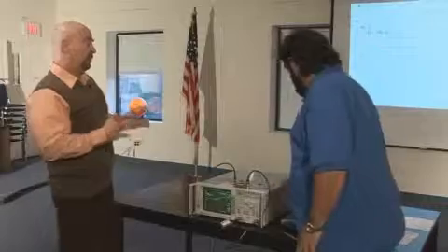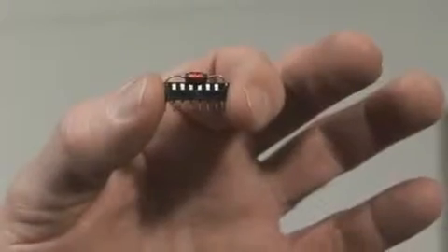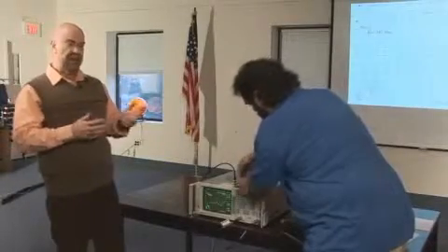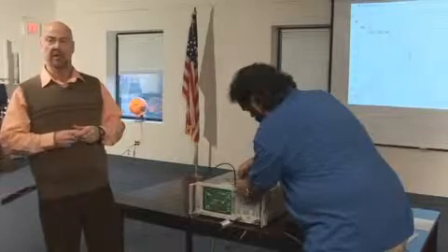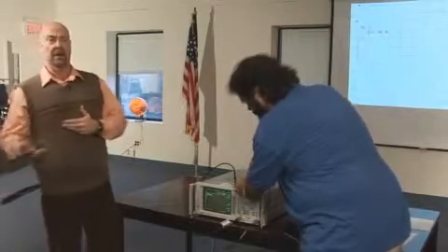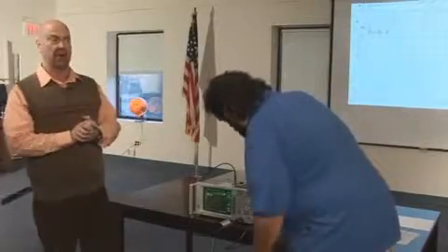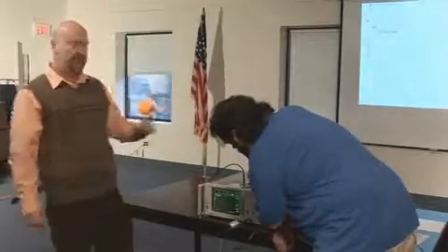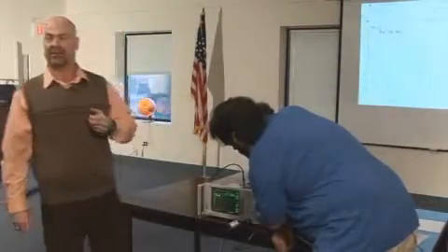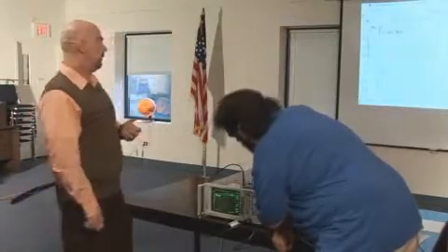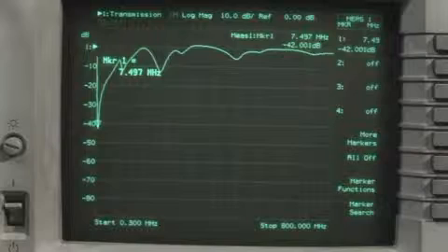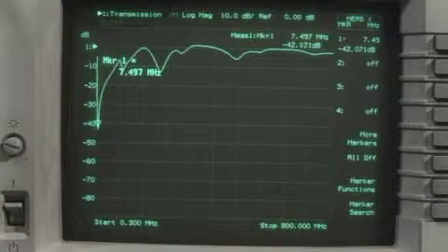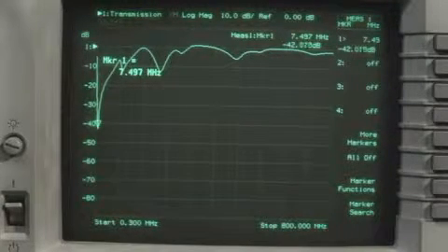One last thing we can look at is an inductor. Steve has an inductor here. This inductor is in series. The impedance of an inductor is 2 pi FL, which is the inverse of a capacitor. So where you would put capacitors in parallel to ground, these you would put in series with your signal, and they will have the same effect as a capacitor. If you look here, this is in series. It almost looks like our original capacitor, where we have a defined notch at 40, minus 40 dB.